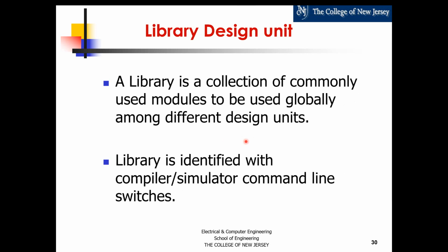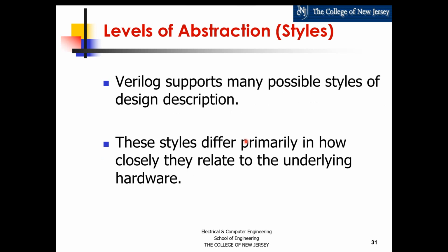So I'm going to keep going through this. Now this is very important. The levels of abstraction in Verilog that are tied to the styles. The key here is to recognize that these different levels of abstraction, or styles, differ in how closely they reflect the actual hardware. At some point, you could almost describe a schematic in a textual way.